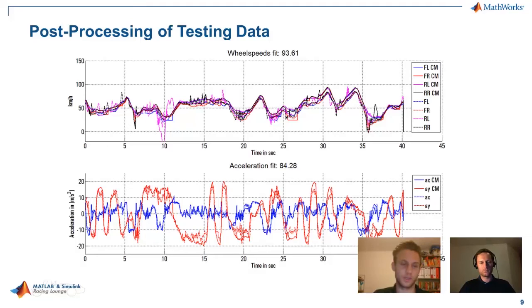You can see the red line is the lateral acceleration and the blue line is the longitudinal acceleration. And if we think back to what Vincent said about the circular forces, we can see here a very good example. For that point, we can see a very high lateral acceleration at very low longitudinal acceleration. Okay, got that. Perfect, makes sense.